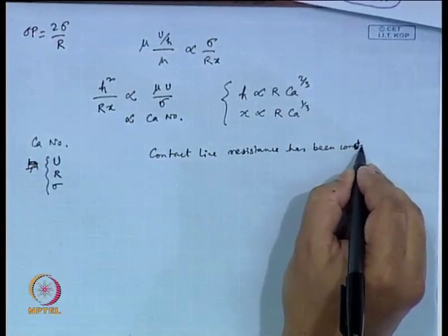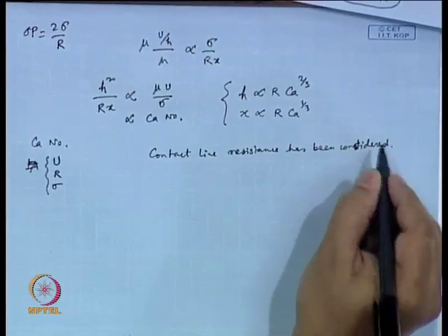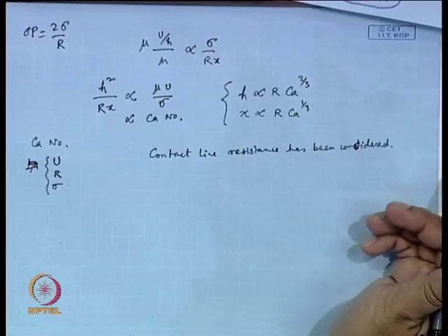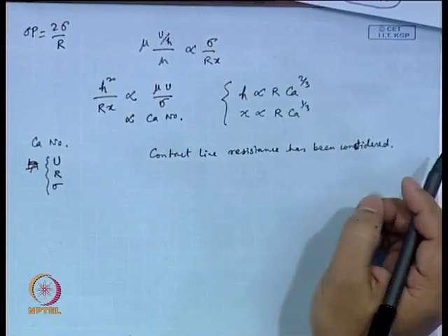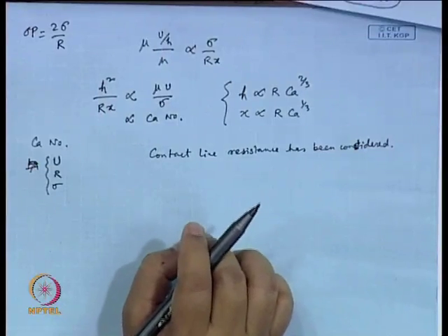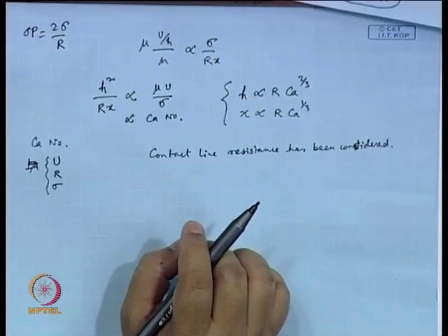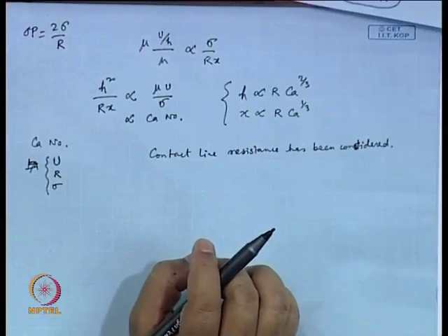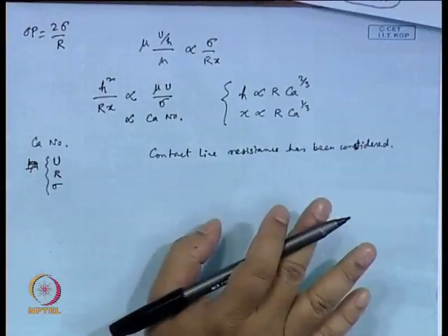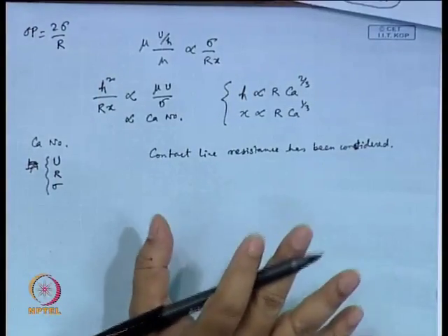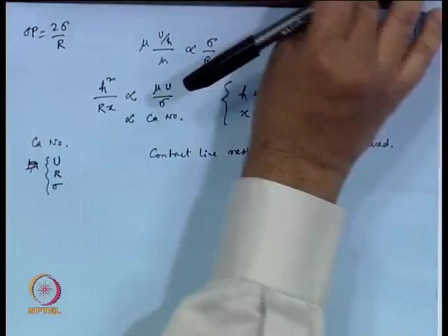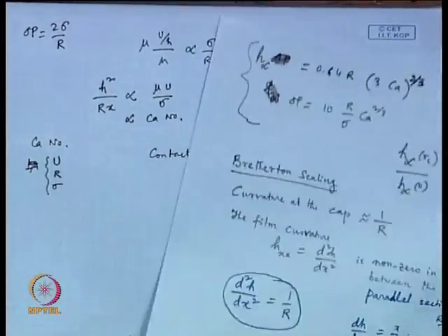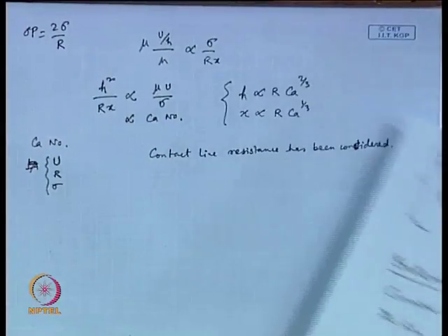Okay. But still, you have a pressure drop because of two immiscible phases present in the channel, but it is not a contact line resistance. Okay. So, that needs to be understood here. We are not talking about the contact angle, we are not talking about the hydrophobicity, etc. We are not talking about these contact line resistances. That is one assumption in this entire analysis, but still you have a pressure drop just because you have two immiscible phases flowing.